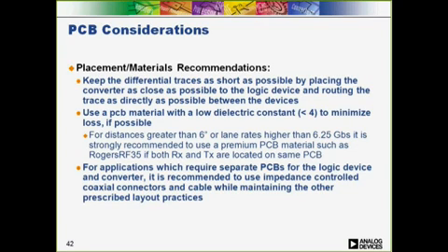Having said that, we realize that most users will be using FR4 material. With proper layout and routing techniques, the use of FR4 material should be acceptable for rates up to 12.5 gigabits per second. We do recommend that the FR4 material have a weave with a minimum spacing between the fiber, since this will reduce insertion loss deviation. If your application requires that the transmitter and receiver be located on separate boards, impedance-controlled connectors and cables should be used.